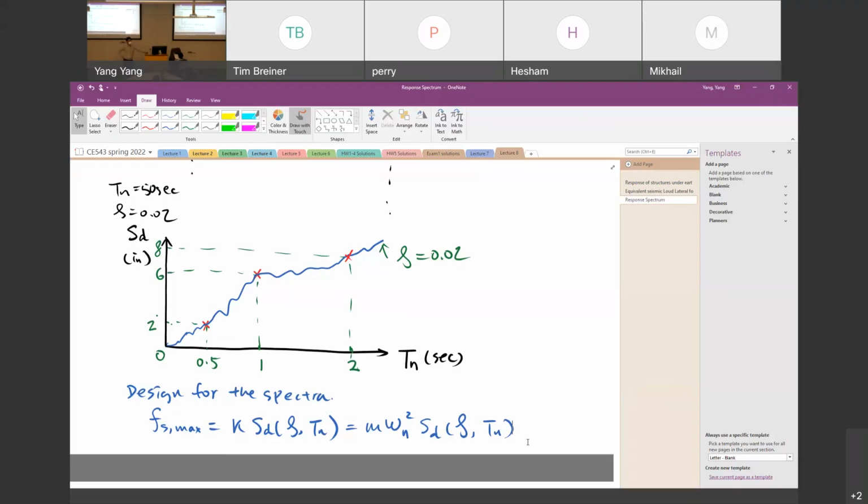In timber structures, we have a lot of gaps between beams and columns, so in earthquakes those gaps contribute to the damping of the structure, as well as the friction between different timber members. So in that case, we may use a little higher damping ratio for timber structures, maybe 4% or 5%. That's just the general damping ratio we can use for design.